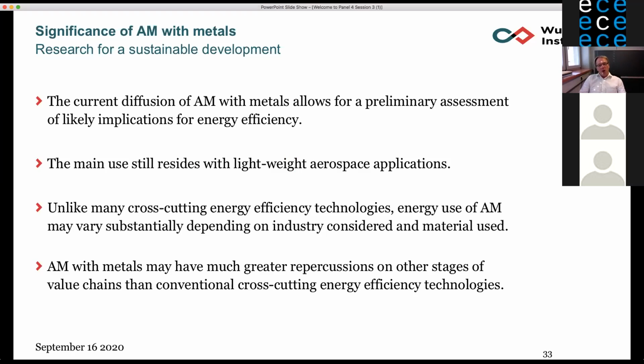And therefore, we saw a lot of application in this area with somewhat bigger, more voluminous parts, which are designed for additive manufacturing. And often the metals aluminum or titanium are used to do this. Steel applications are not at all common in aerospace, of course. But we can also imagine, I will come to that later on, applications where steel may also play a role in additive manufacturing.